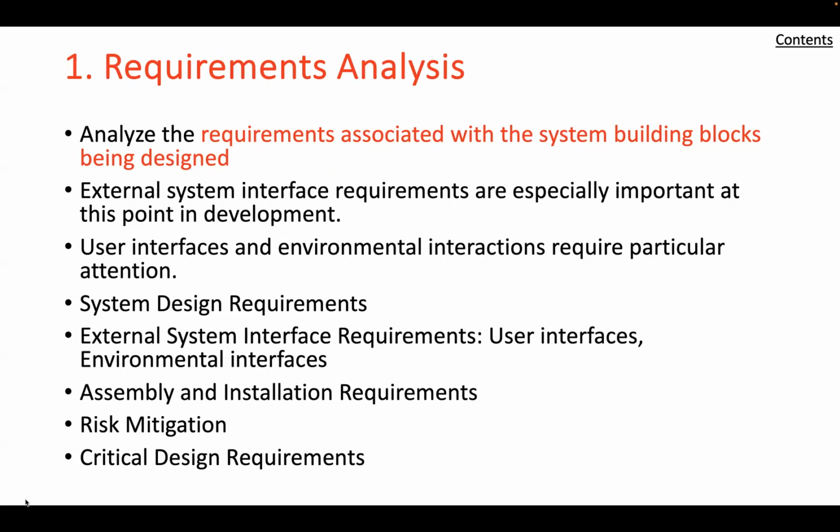Then we also have environmental interfaces. In defining external interfaces subject to shock, vibration, extreme temperatures, and other potentially damaging environments, it is essential to again consider all stages of the system's life, including production, shipment, storage, installation, operation, and maintenance, and to anticipate all of the interactions with the environment during each step.